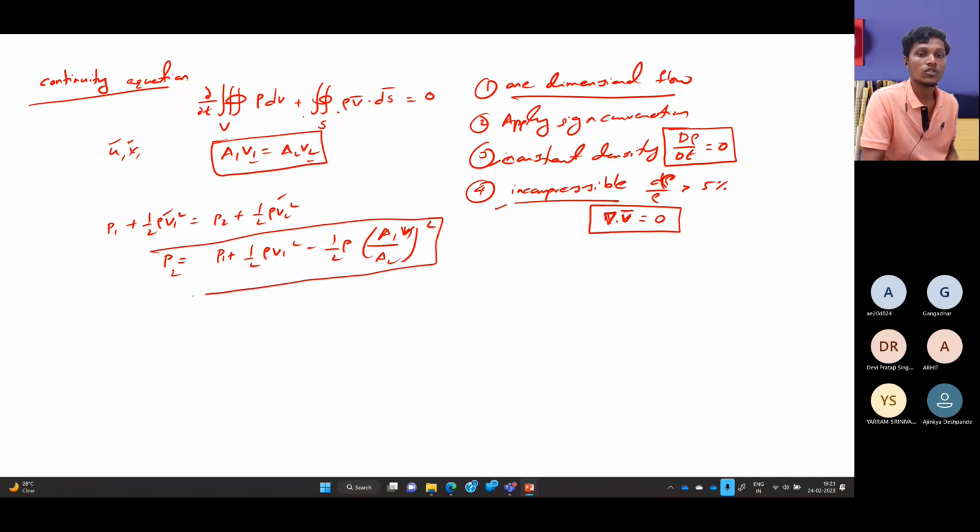So now we just substituted it, and this is a coupled form of the Bernoulli and continuity equations, which will be useful many times in calculating the flow that aerodynamicists usually encounter in real life or for experimental purposes. This is a very common kind of equation, valid only for subsonic, incompressible cases, and all these conditions we have seen must also be applied.